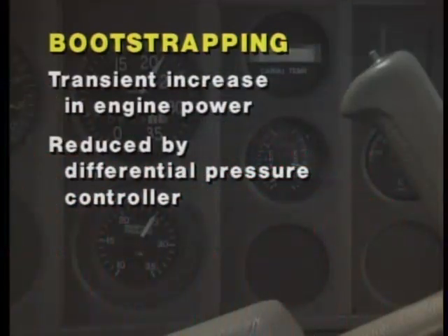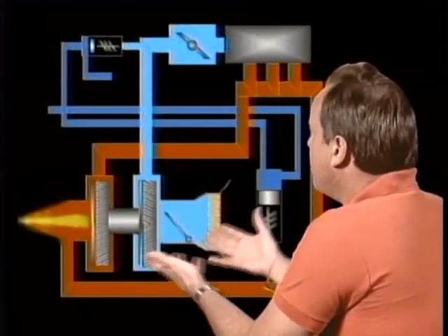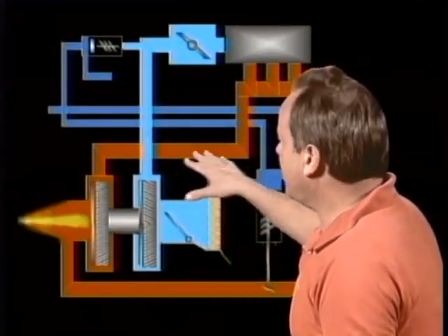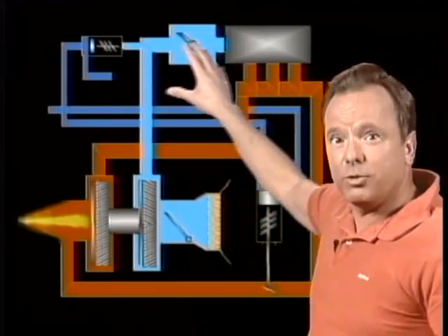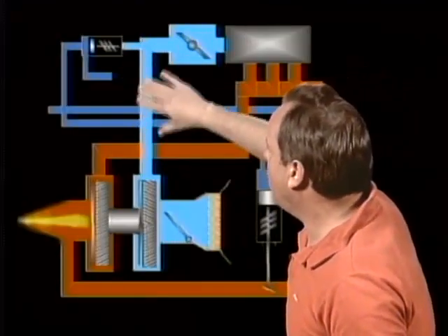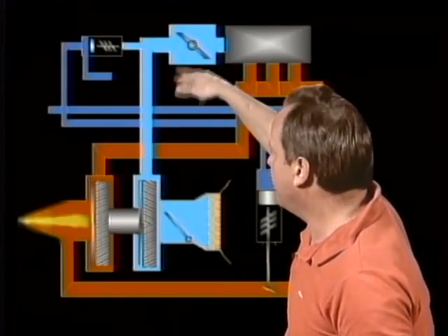A turbo-normalized system is one in which you just keep ambient manifold pressure at sea level all the way up to higher altitudes. It makes the engine think it's at sea level even though it's really at a higher altitude. Now, there is a different set of controllers in that engine then. You have an absolute pressure controller, and what it does is it says, look, we're going to put, we'll say 29 inches of manifold pressure on this airplane at all times before it gets to the throttle valve, the upper deck.